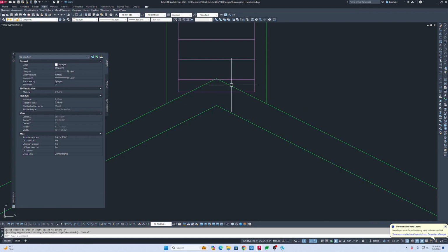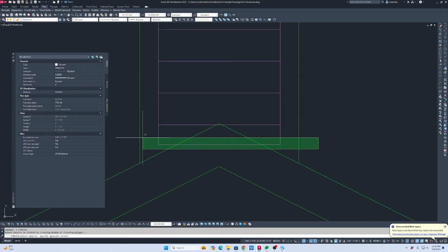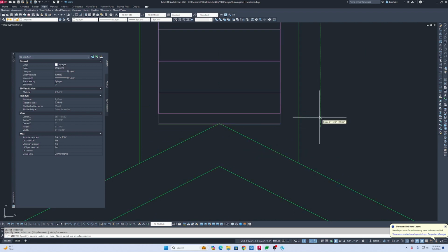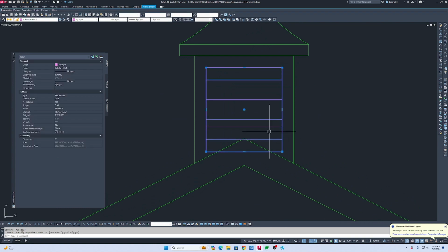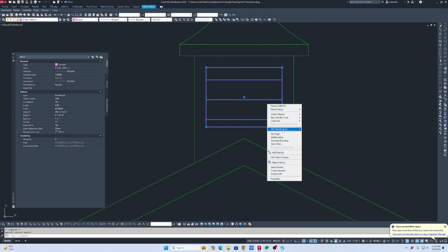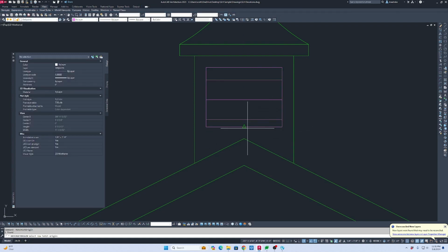Yeah, okay. Close that. And this guy, we don't want to cut that vent off, so let's go up to the top, and then let's do a 3.5 inch offset. Why? I must not have my hatch turned on with associative. That is annoying. Let's try and re-origin that. Do it at the bottom.